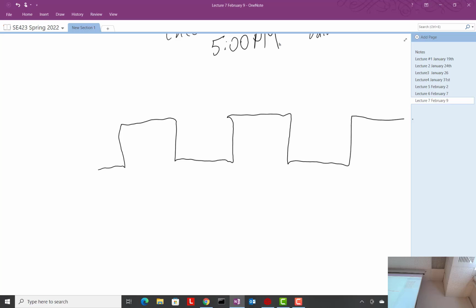Okay? So that's this idea of PWM: if we tell a motor to go positive 50% of the time and negative 50% of the time, it's almost like the motor's seeing an analog 0 volts. Even though really that motor is seeing, let's say, 24 volts. It's seeing positive 24 volts, then it's seeing negative 24 volts. But because of the time constant of the motor, it's as if the motor sees 0. Because with PWM, the carrier frequency, the frequency at which we're turning on and turning off, is so fast that the motor doesn't have time to move because of its time constant.